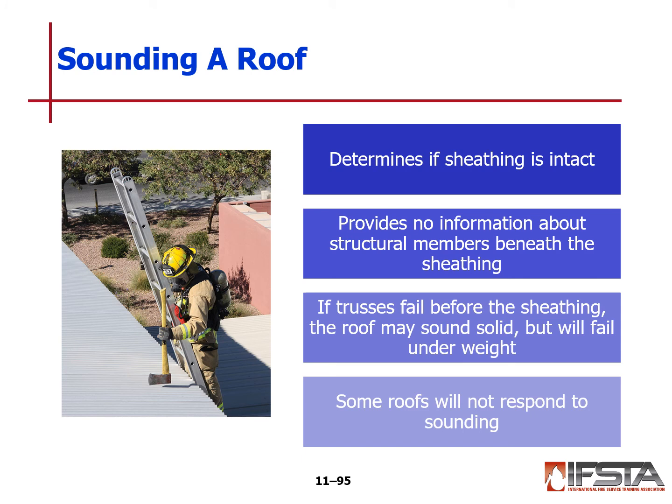Sounding the roof. You've heard this term. I talked about it a couple times. Before you step off of that ladder, you want to use a tool and sound the roof. This determines if the sheeting is intact. It provides no information about the structural members beneath it, however. If trusses fail before the sheathing, the roof may sound solid but will fail under the weight. So they can still sound solid and fail. Some roofs will not respond to sounding.